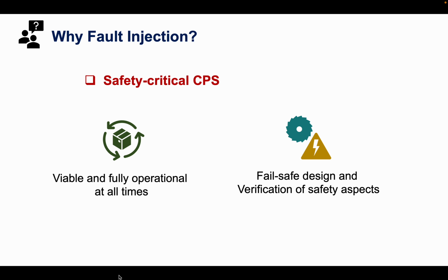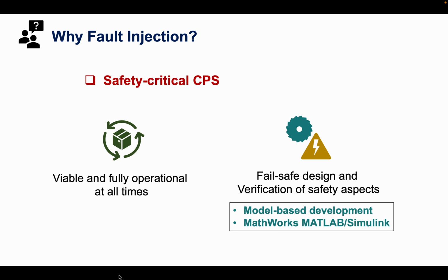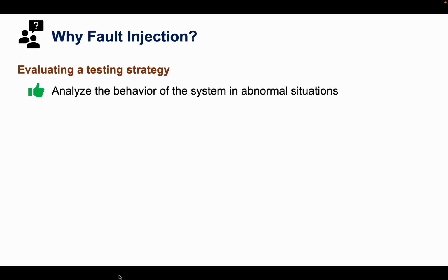For the fail-safe design and verification of safety aspects of such systems, researchers are relying on model-based development around the MathWorks MATLAB Simulink environment. Usually, a testing strategy is evaluated by analyzing the system behavior in abnormal situations. For this, industrial safety standards recommend fault injection and mutation testing.